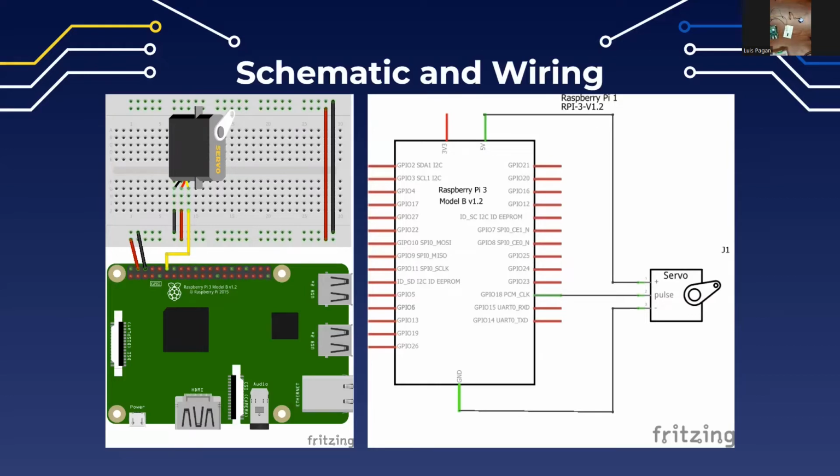Usually, you'd want to apply a separate power source for the servo, and then just plug in the logic to whatever controller you're using. But for this demonstration, and when you guys are doing your robot, you can just plug it into VCC and ground supplied by the Raspberry Pi.